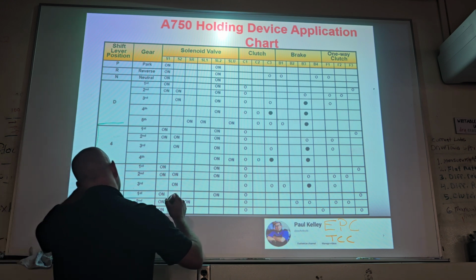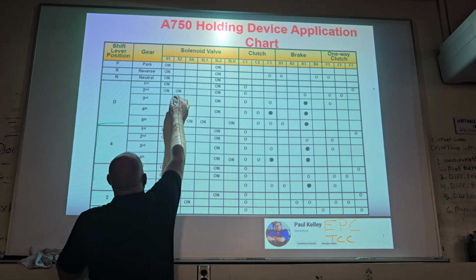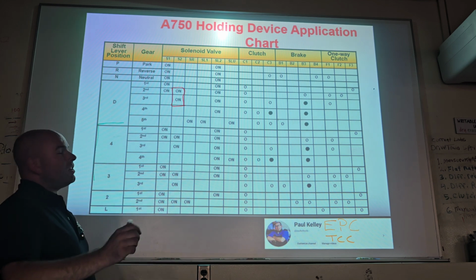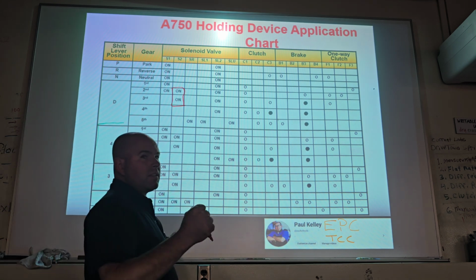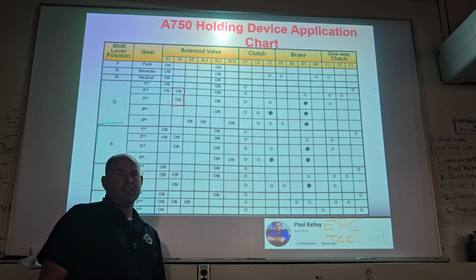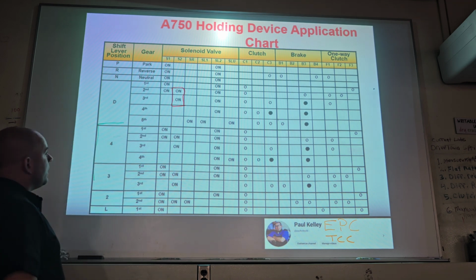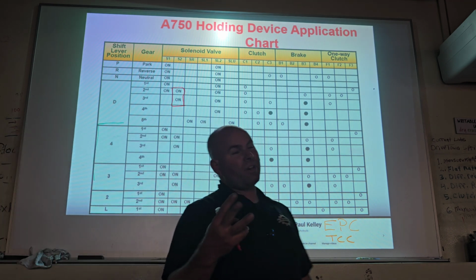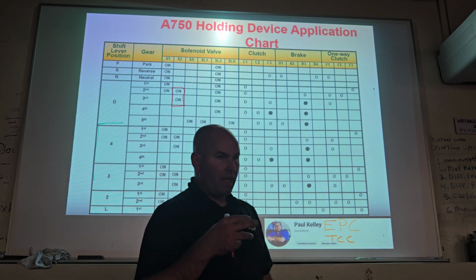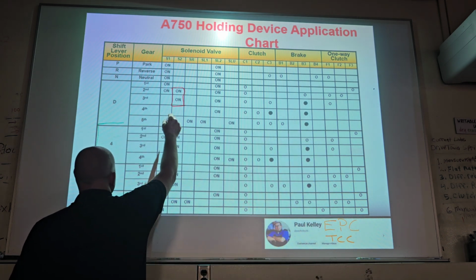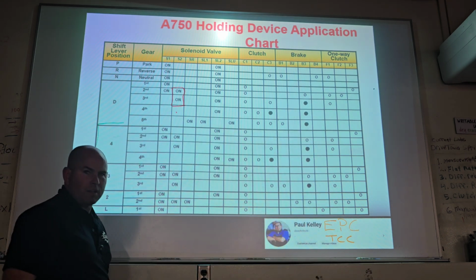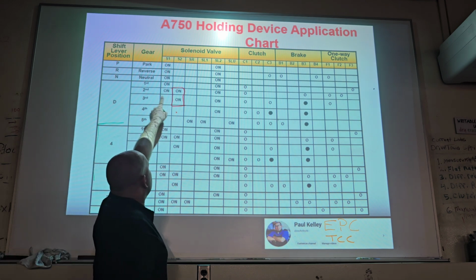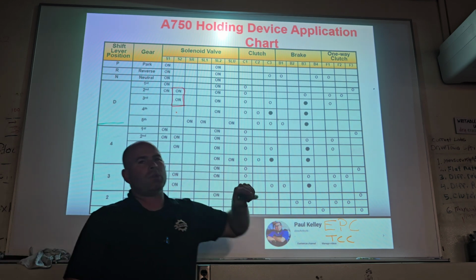I'm going to highlight them. Would first work? First, and then it'd be like, no second? Probably generally no. You might have some instances where that sets a DTC though, and it goes into limp home, and instead it commands it to start in fourth. Make sense? But generally, if S2 were to not work, it's not that second and fourth would slip though.